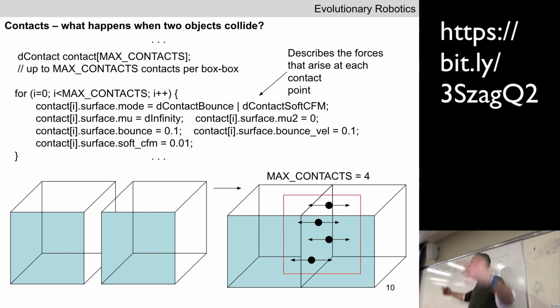Let's imagine you're going to simulate two bullets that have been shot at one another. You set the time step pretty low because you've got very high velocity moving objects, but they're still doing this. You can get into a situation in a physics engine where the two bullets do this, then this, then this, then this. There was no collision detection and resolution. The objects never approached one another, or they never got close enough for collision resolution.